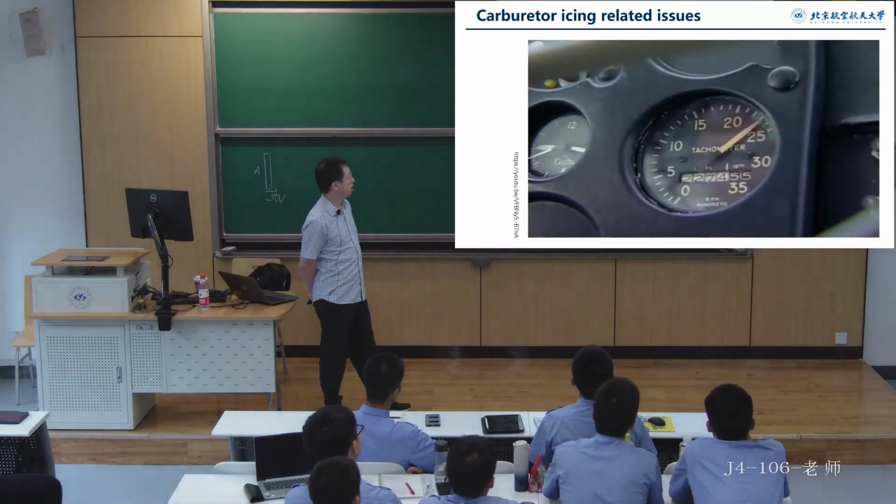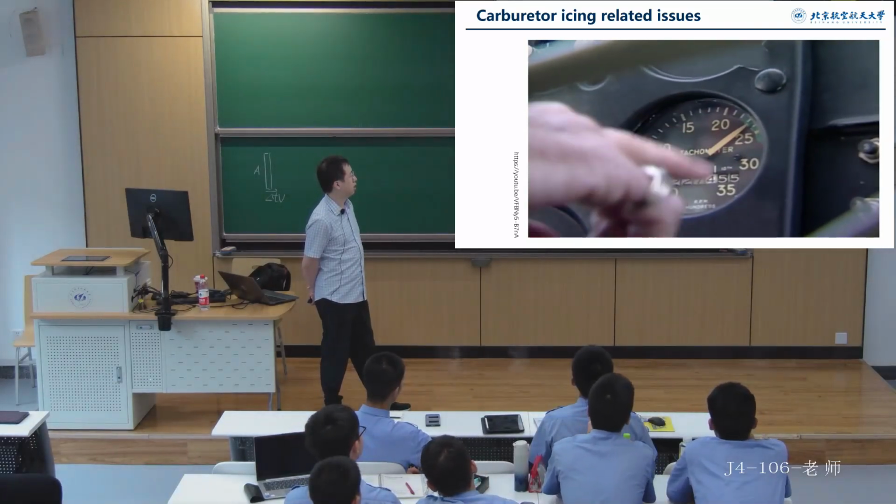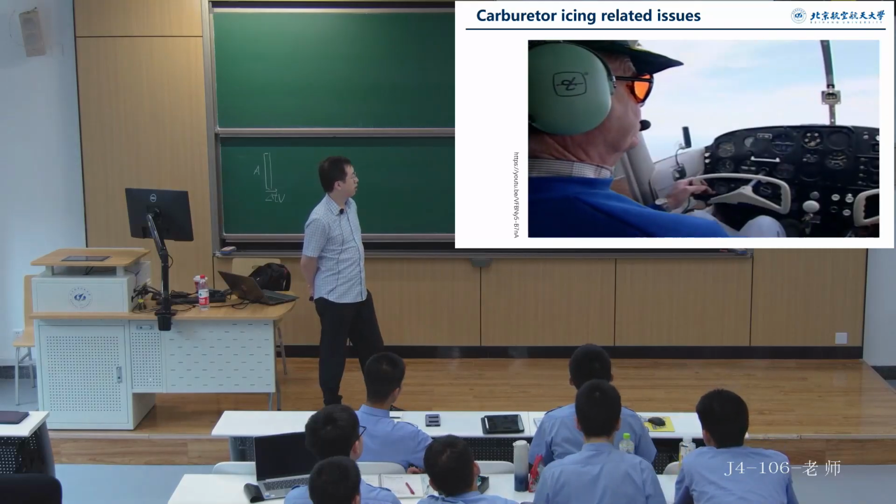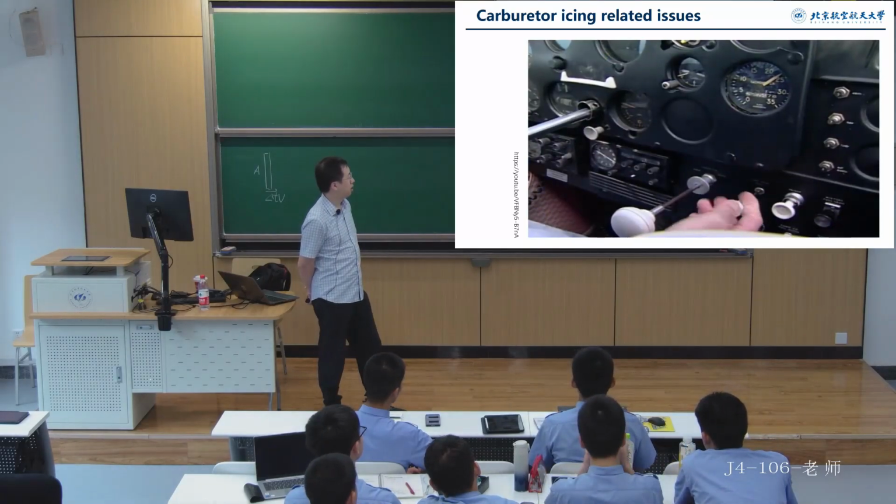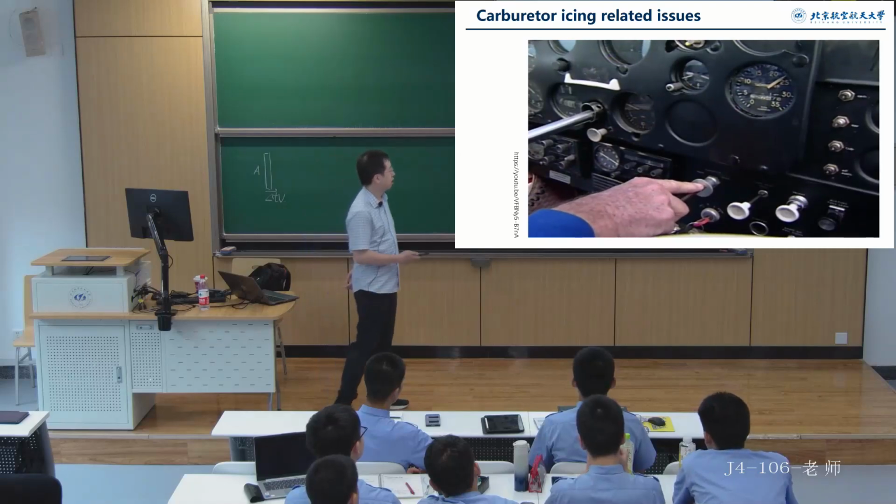The first sign of carburetor icing may be a slight reduction in the RPM of the engine or a loss of manifold pressure. By applying carb heat, a flow of heated air from the exhaust melts the ice and eventually allows...